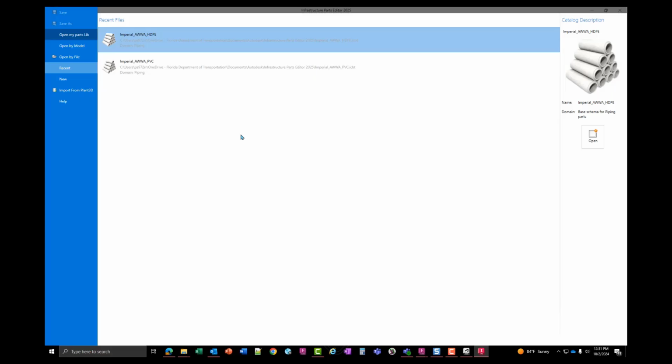I think it's two separate export options, but for our usage, we're going to be exporting as Civil 3D, and then we're going to create a new parts list. One thing to remember on Part Builder parts list and Inventor parts list is they're not cross-compatible.